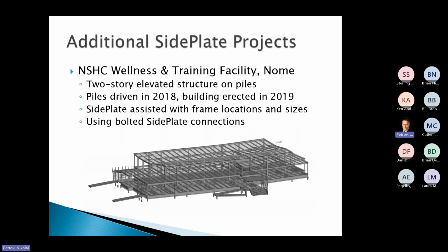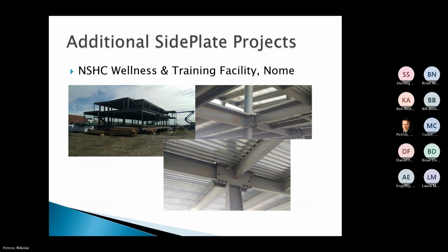We used the bolted connections for this. Basically, since they brought the bolted connections online, I think that's all we've used. So there are some pictures. You can see here the bolted connections of the SIDEPLATE frames. And it's funny, just from looking at the frames, you see they're not quite as big as in Anchorage. We're out in Nome. It's wind governed. We've got some seismic, but it's always funny. If this were in Anchorage, it would all be a lot bigger. But yeah.